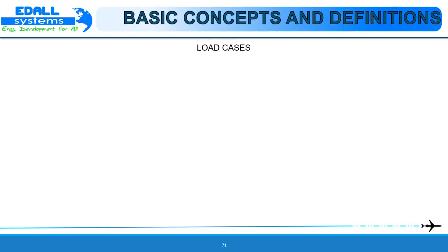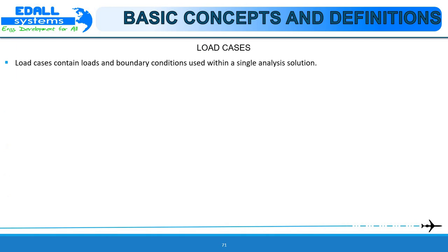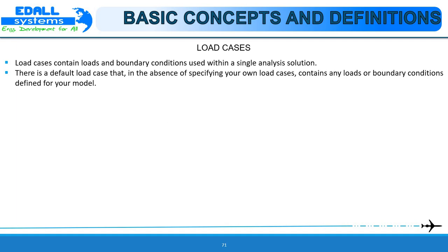Load cases. Load cases contain loads and boundary conditions used within a single analysis solution. For example, one load case may represent the loads and boundary conditions for each time point in a time-dependent analysis, or a single state of load for a static problem. They are central to the ability to perform complex analysis on an individual model or examine multiple states of loading and behavior within the same model. There is a default load case in the absence of specifying your own load cases, which contains any loads or boundary conditions defined for your model.